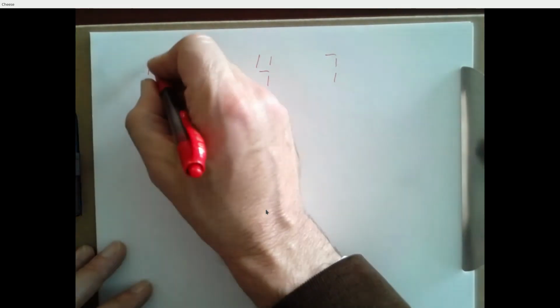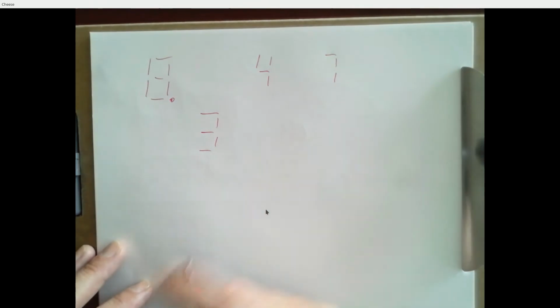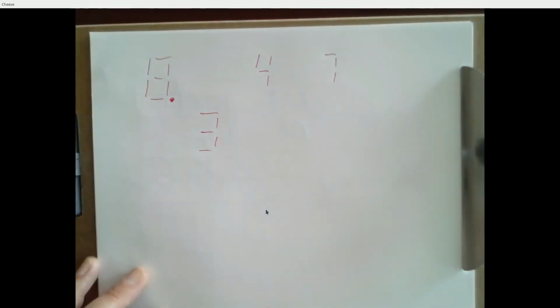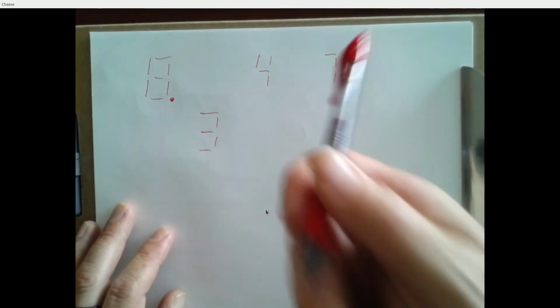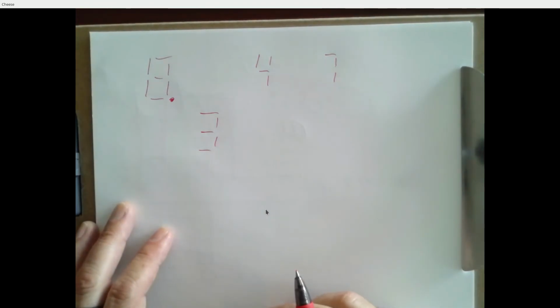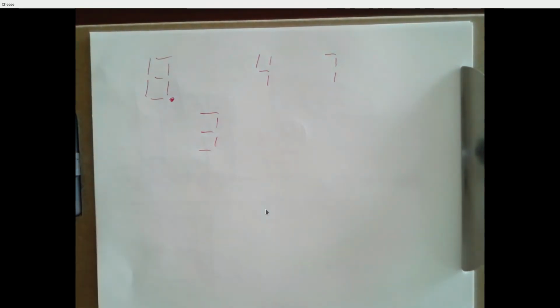So you've got 7 segments, 7 LEDs up here. We won't worry about the decimal point. We label them A through G, and by turning certain of them on, we can make this display look like it's displaying a number. Your goal when you build your 2-bit adder is to display your sum using this display.